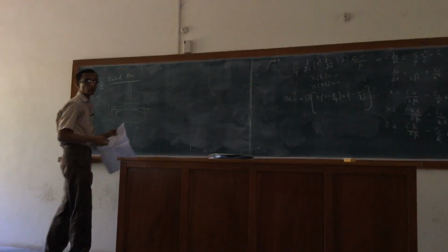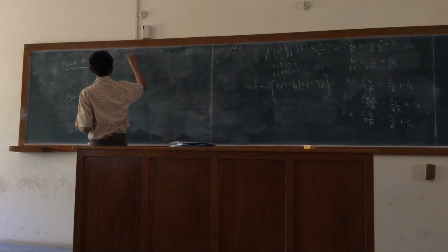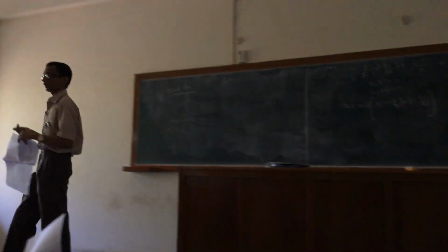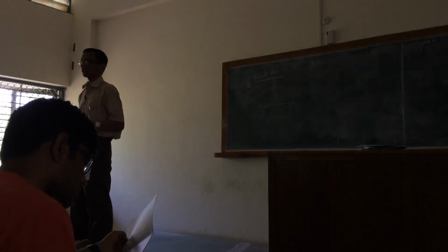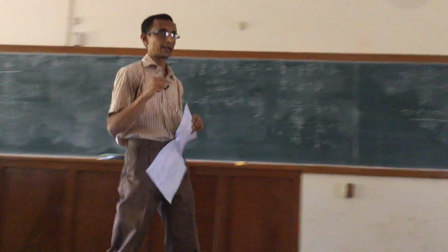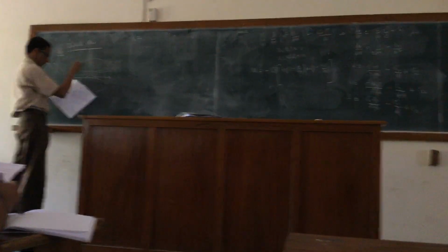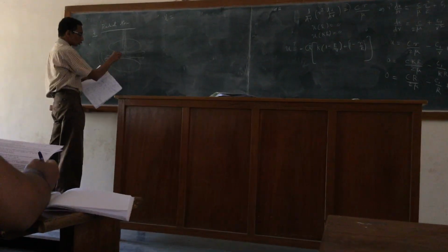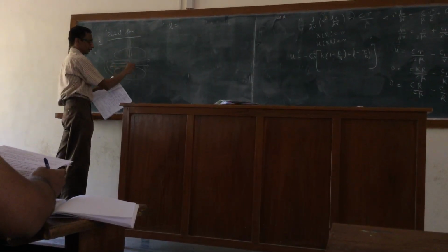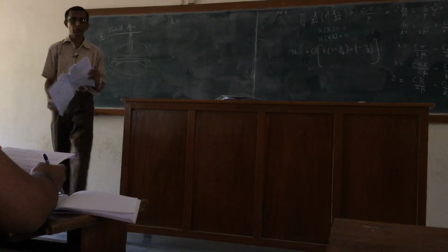Again, you have to assume creeping flow. So this is the case in cylindrical coordinates. We have now very much exhausted all three possibilities of one-dimensional flow. Seeing flow down a circular tube, v_z is the only component. Seeing fluid between two cylinders that is rotated, predominantly it is v_phi that would be dominating, right? And here you are asked to assume that the fluid is coming in here, in a creeping, radial flow outward through the space between the discs. So fluid is coming in here and then going out.